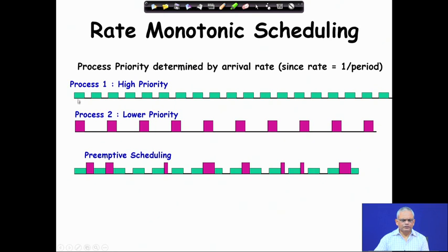At time 0, both task 1 and task 2 instances are ready, but task 1 has higher priority and therefore this instance starts running. The task 2 instance has to wait, and as soon as the task 1 instance completes execution, the task 2 instance starts running.